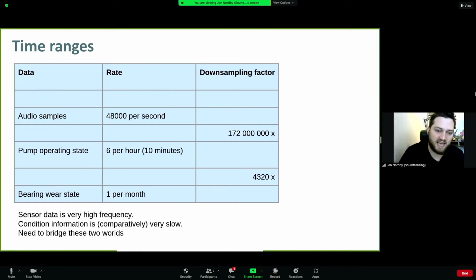Basically our edge challenge is: where is the boundary between our edge system and our cloud system, especially when it comes to the data rate? What is the data rate that we are transmitting between these? Because this influences the cost of transferring data. It influences what radio or transmission technologies are available. And it influences the battery lifetime, because sending data tends to be one of the most energy-costly things that the sensor does.